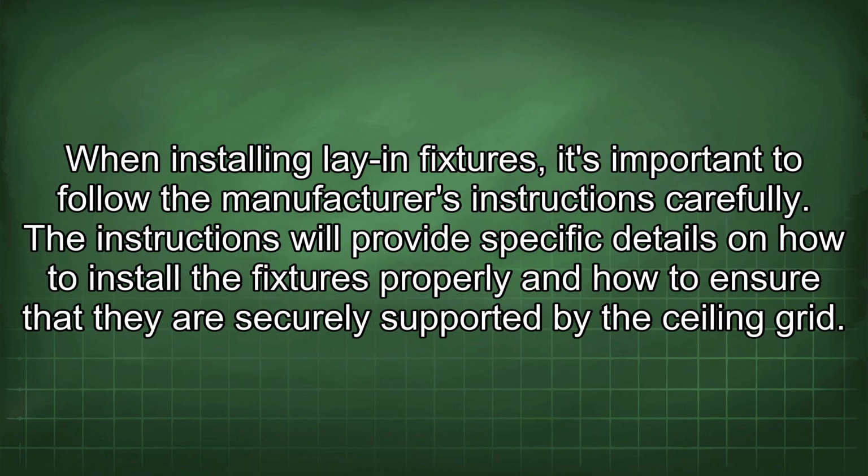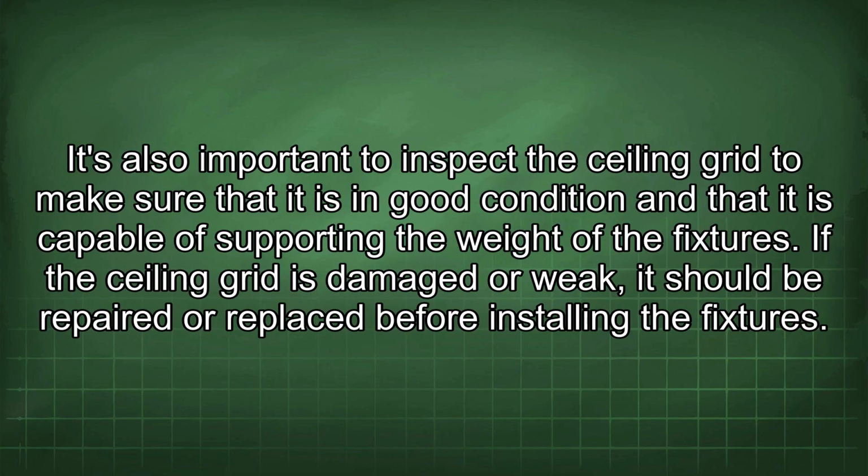When installing lay-in fixtures, it's important to follow the manufacturer's instructions carefully. The instructions will provide specific details on how to install the fixtures properly and how to ensure that they are securely supported by the ceiling grid. It's also important to inspect the ceiling grid to make sure that it is in good condition and that it is capable of supporting the weight of the fixtures. If the ceiling grid is damaged or weak, it should be repaired or replaced before installing the fixtures.